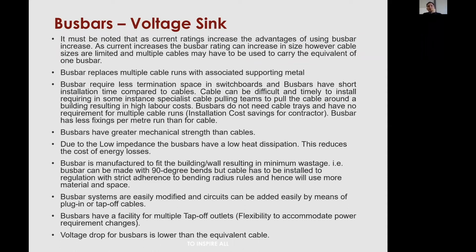It is in effect actually a point bus bar when you do that, and it doesn't create the same voltage sink idea. Now, I use the word sink here like a drainage sink quite deliberately, because that thick copper bus bar from the previous picture is doing exactly that. It's actually drawing all the voltage together so that they can always be at the same level, the same voltage.